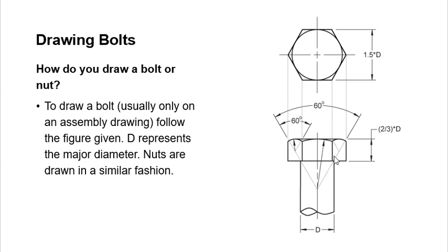And here, of course, that's from the top view, so you can see it from the front view. From here to here is going to be 1.5 times your diameter, how wide the head is. This one is how tall the head is. And we are calculating with the value of the diameter, from here to here of this rod of that bolt. So here, that is your bolt, and even though we draw the top, we can also use it as a nut, because this has got to go into this anyway, because bolt and nut fit each other.